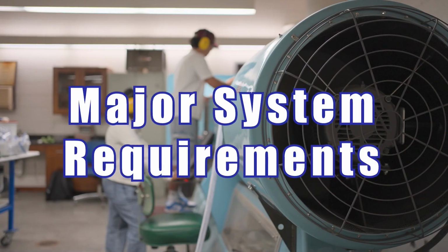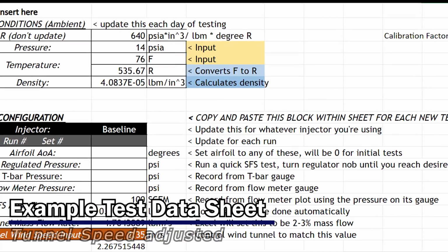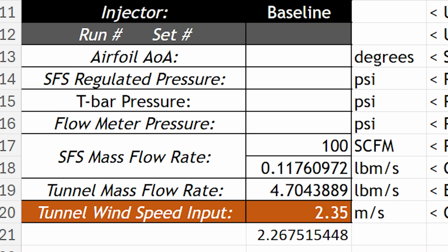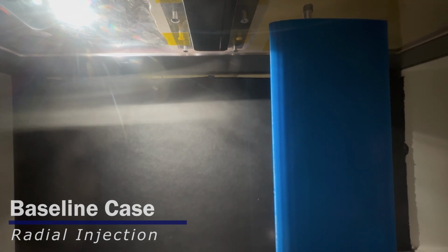We were required to recreate the Honeywell injection problem. For our injector design, the mass flow rate of the SFS was required to never exceed 2 to 3% of the flow rate of the wind tunnel itself to more accurately simulate the conditions in the compressor. We were also required to reduce the adverse pressure gradient caused by radial injection by at least 40%.